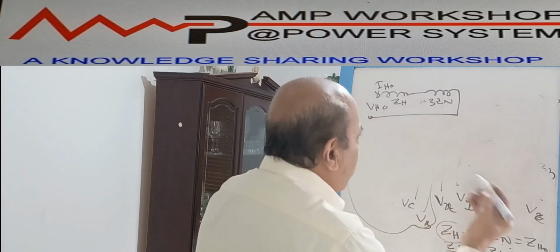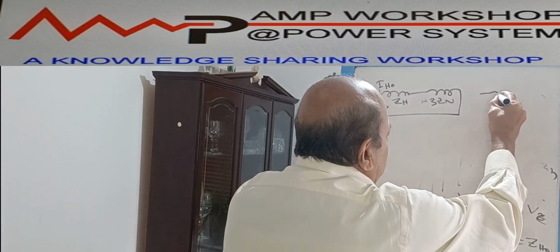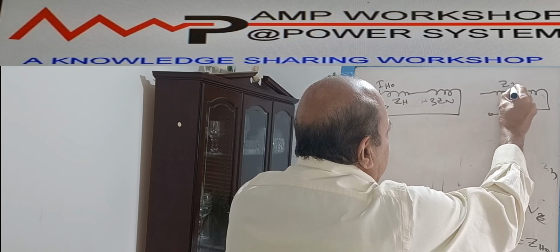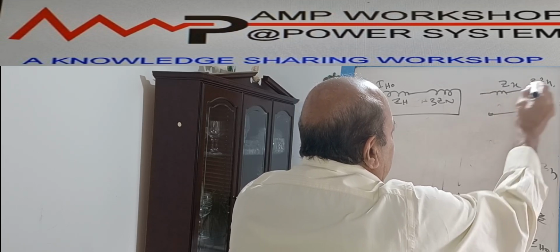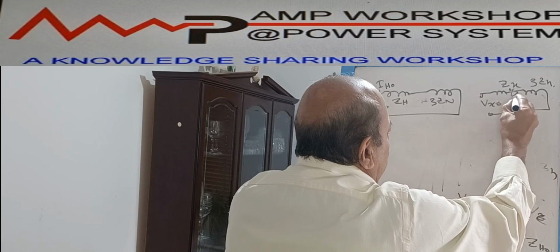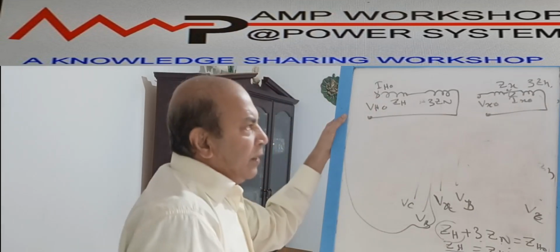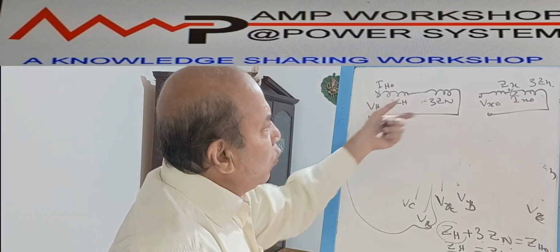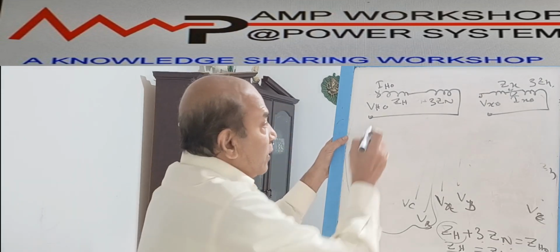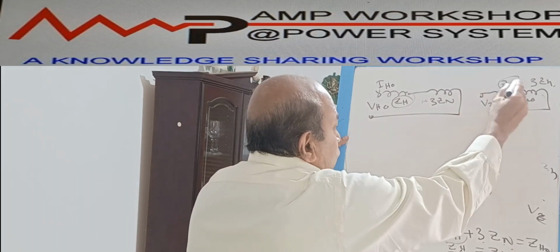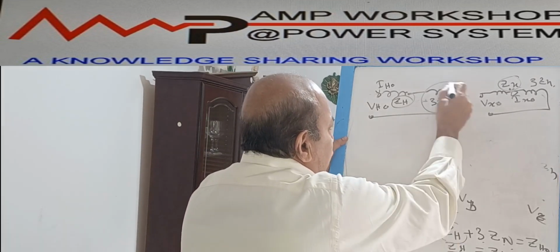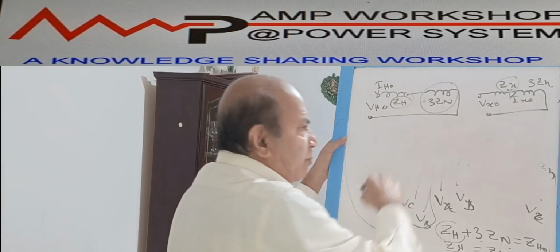Now if you go to the low voltage side, that will be a similar network, with ZX and 3Zn. Here we are applying Vx0 and the current going is Ix0. Right? Now with these two networks we have done the equivalent circuit for the transformer. The phase impedance we can convert to either the primary side or the secondary side. Similarly, the neutral impedance of both windings we can transfer to one winding.